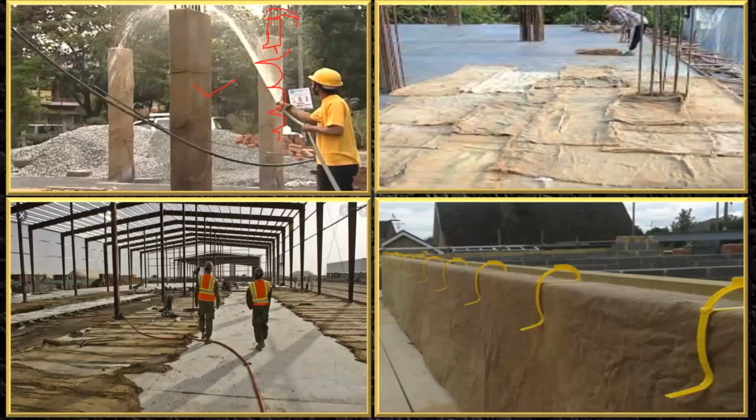Otherwise, nowadays a few people tie a big polythene sheet here. In the polythene sheet you fill the water, and a small hole is made in the sheet. Through that hole, small drops of water keep sprinkling on the surface of the column. Because of this the curing will happen, and there is no loss of water from the inside of the column, right? So these are different ways and different techniques of doing the curing.